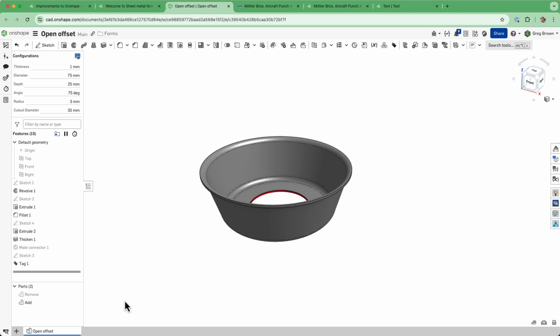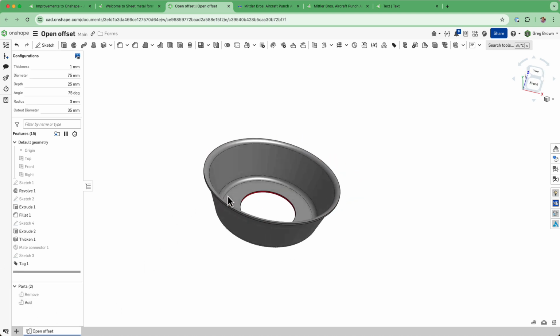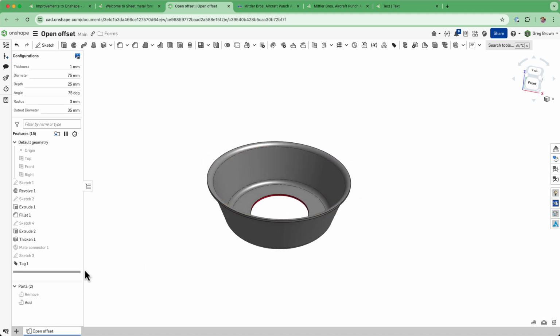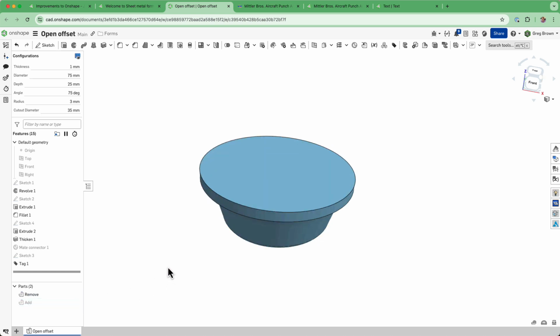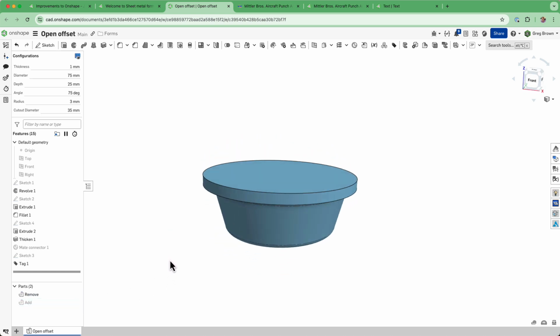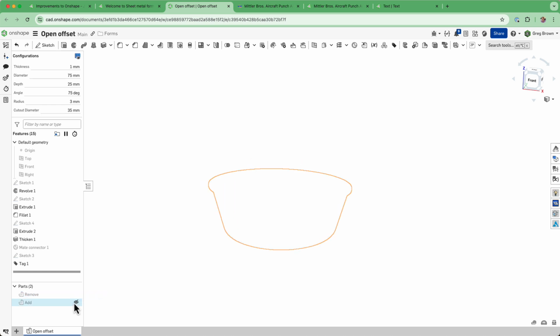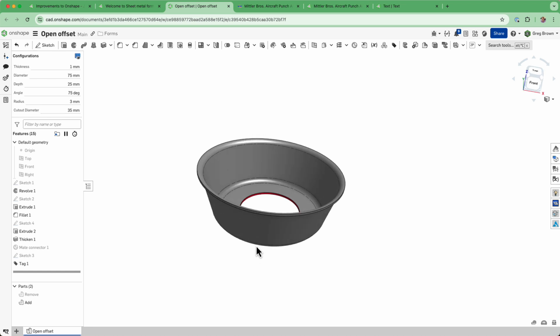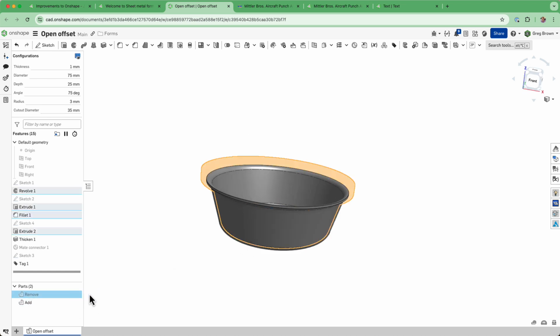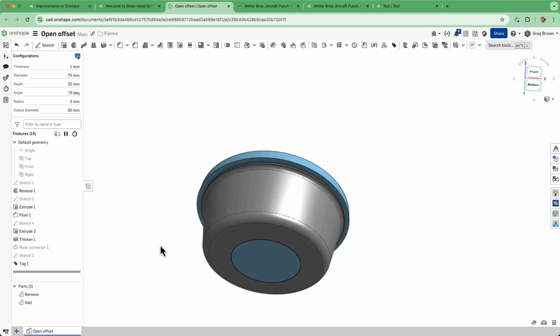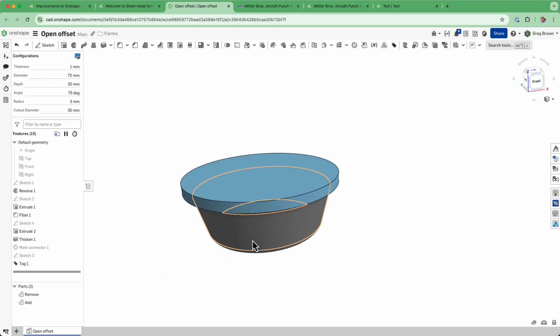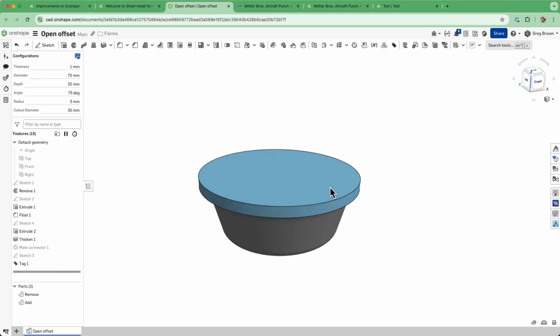What you need to do is you need to create a part studio, and in that part studio there's a few prerequisites. One of them is a part which you're going to designate as the removal part, kind of the tool which is effectively going to boolean out or remove material from your sheet metal part. And then you can optionally, depending on the shape or the style of sheet metal form, you have another part which is the bit that's going to get added in. So you've got two parts. In this case, a removal part and an adding part. Now that is the only geometry you need.